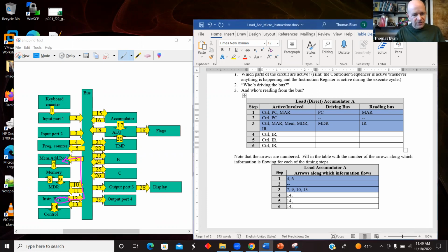So in addition to the 14, if I'm following my flow, there's a 12.6. And then let's say who's involved. The instruction register is involved, because I need to know what instruction I'm executing, but it is also playing a dual role, telling me what the instruction is, but also being enabled and putting its value onto the bus.